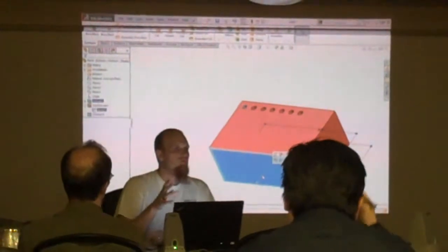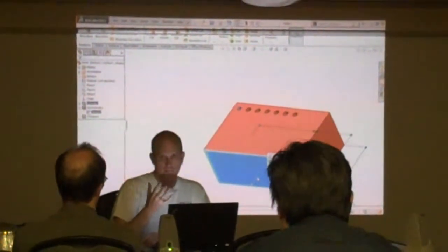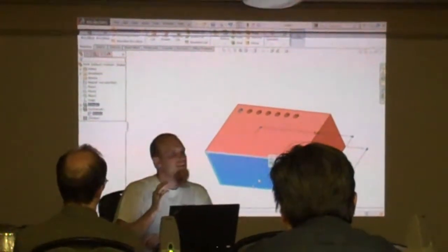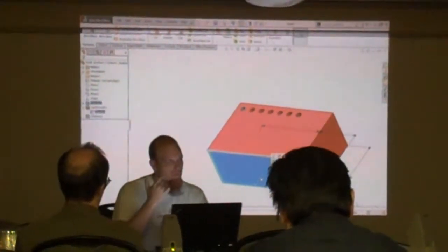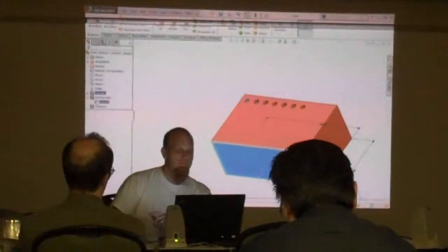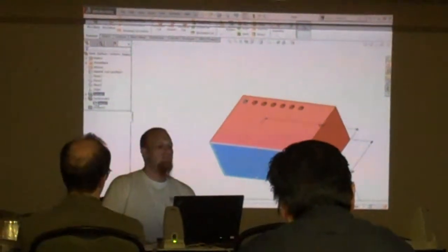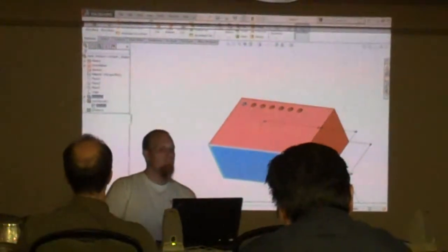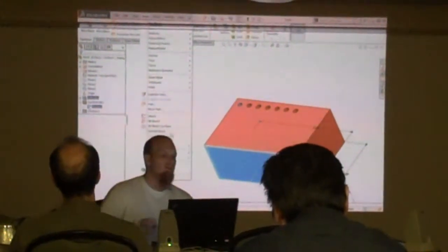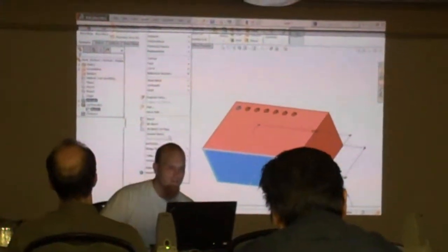Basically, derive, another word for it, is clone the sketch. They're exactly the same. They will always change with the parent, because you can't change the children. So I have control selected the sketch, I control selected a face. Again, it could have been the top face if I wanted to. Insert, and now it's alive and not grayed out. I give it an OK.